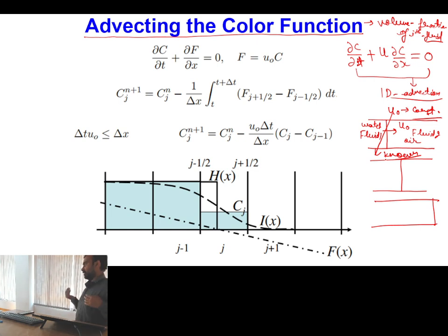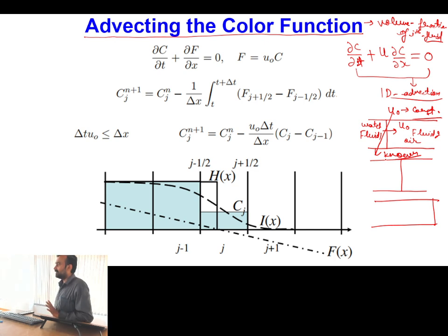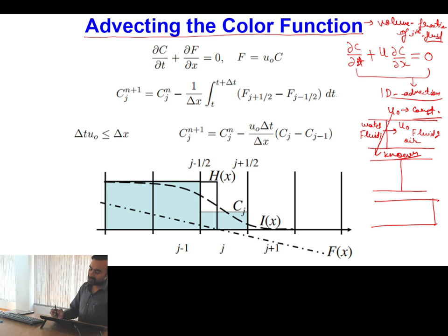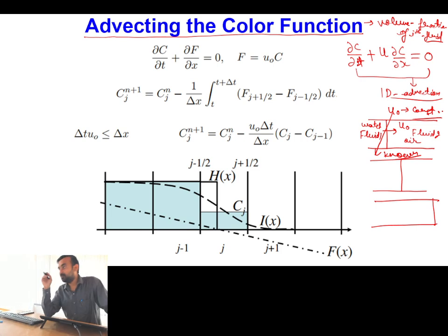It will have some parabolic type of velocity profile, but at the moment we are taking the assumption of one dimensional flow. In this assumption we are assuming that at every cross section the velocity of water is the same, u naught, which is constant and not changing along the x direction.